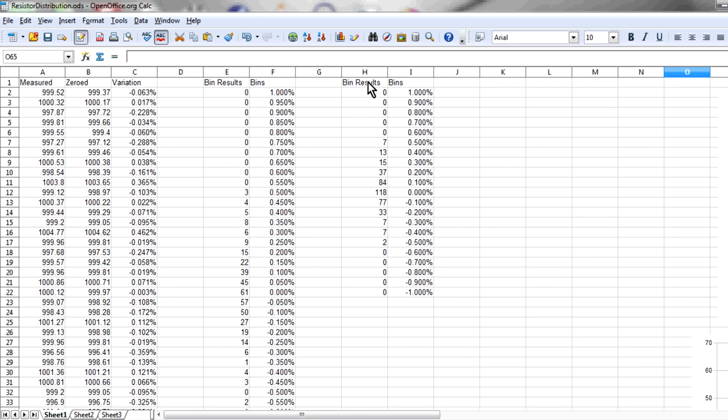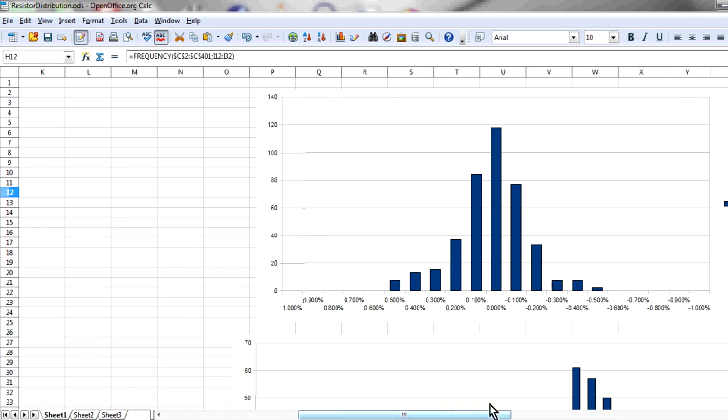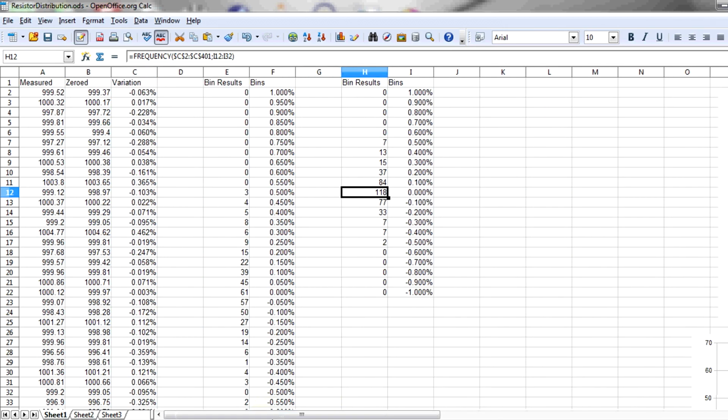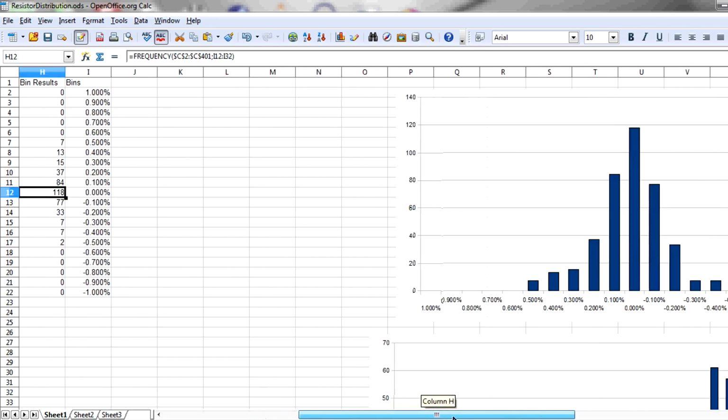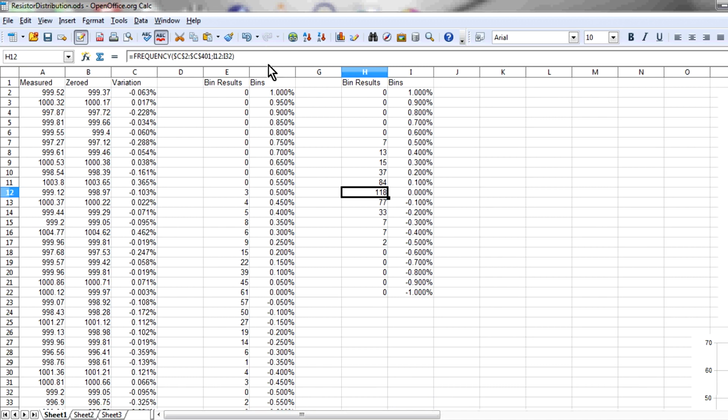But when you're doing frequency analysis like this, you're left with fewer and fewer actual items in each bin when you convert it into the frequency domain like that. Now, we can change this by increasing the number of bins we've got, and that's what I'll do over here. But then you effectively halve your number of data in that particular bin.